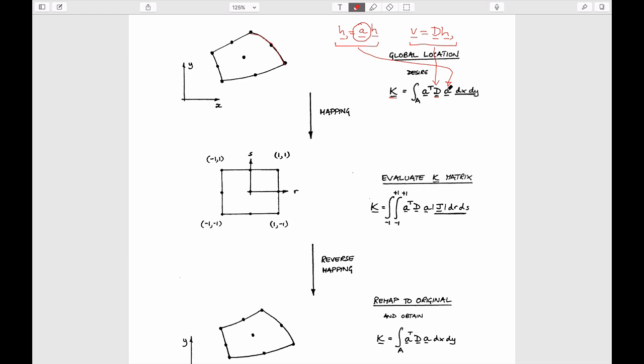And so the net result is that we can take this integral and write it like this, in which case we don't have to deal with it. These are all constant, they come outside the integral. We can just calculate what the integral is, which is just the area of the triangle times its thickness, or the area of the prism times its thickness as well. That's all this integral says.